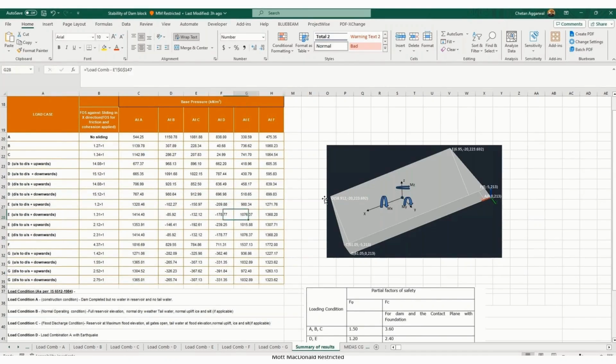But then again redistribution will also occur, right? So let's be on the conservative side. If negative pressure magnitude is half of this, then also we can consider that the footing is safe. So in our case 1368, and say 1000. In our case negative pressures are much lesser now, so this should be okay as per that criteria.